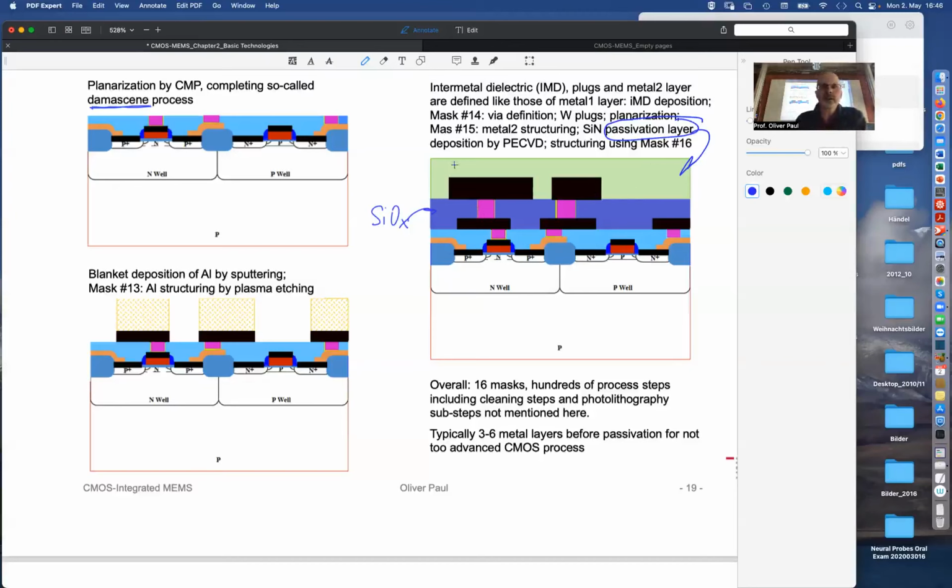And this silicon nitride now covers the entire wafer, but of course, then everything would be encapsulated and you couldn't run the chip because you wouldn't be able to get any signal in or signal out. So at some locations out in the periphery of the chips, the silicon nitride needs to be opened.